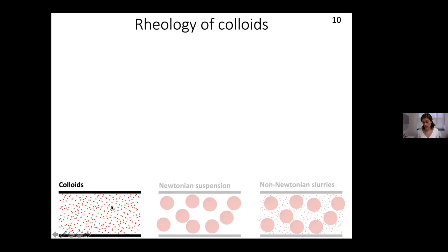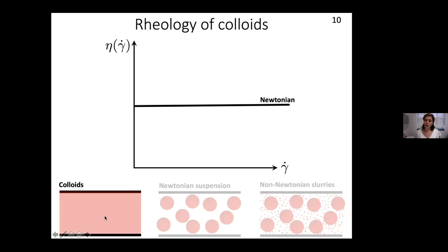Suppose that there are just fine colloidal particles in the system, and we know from colloidal science that these particles interact with hydrodynamic, contact, and surface forces to form a substrate whose rheology can be expressed by non-Newtonian laws, generalized Newtonian laws, for example, shear thinning, shear thickening, and yield stress fluids, or viscoelastic laws.